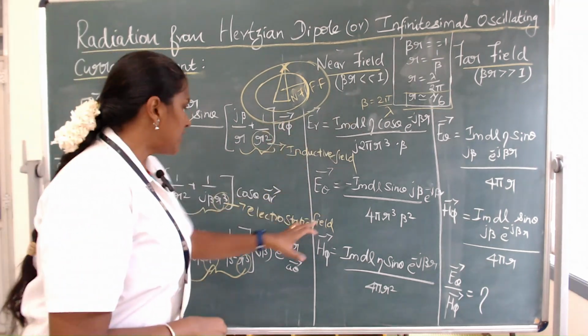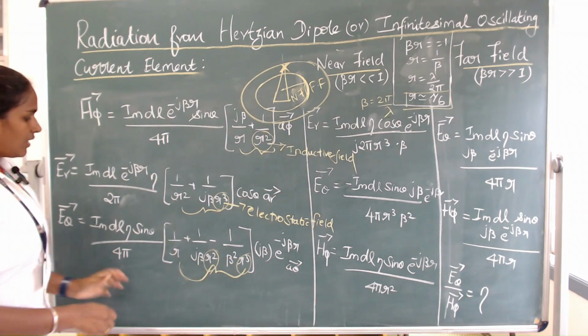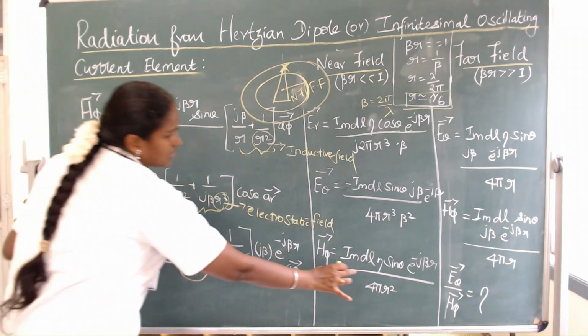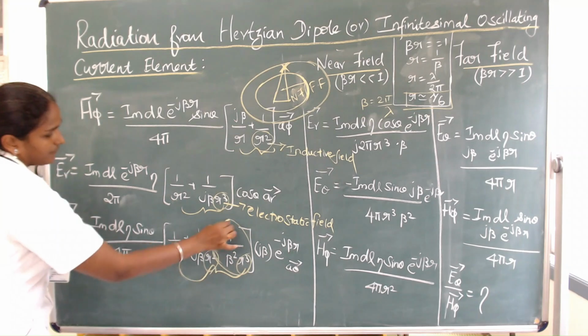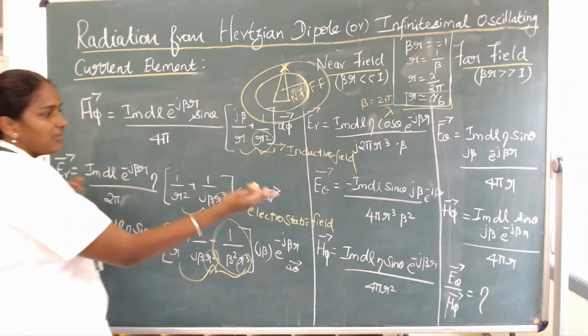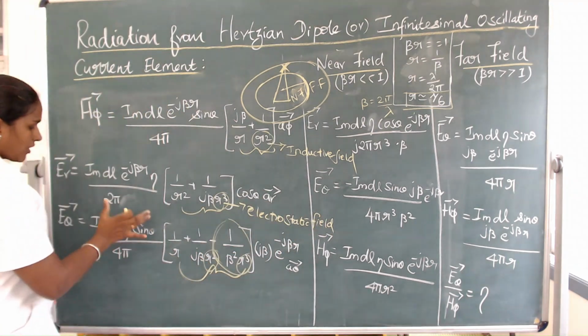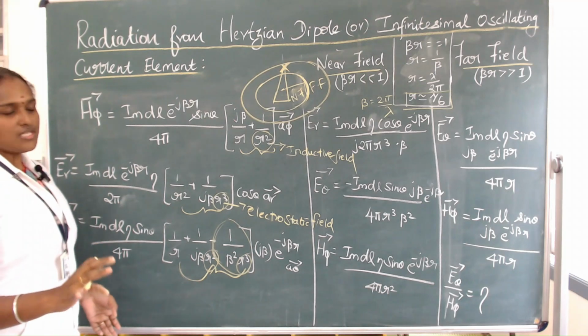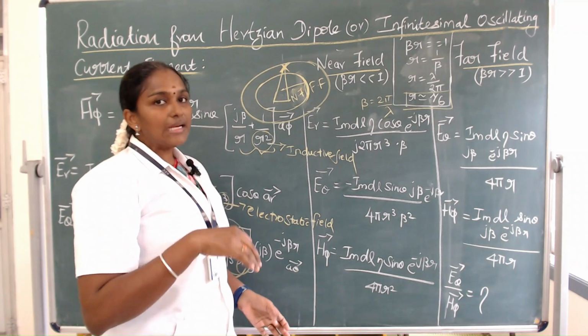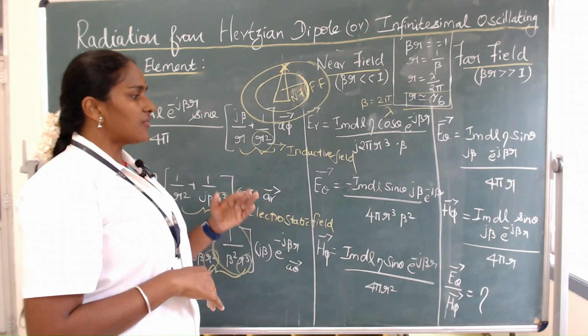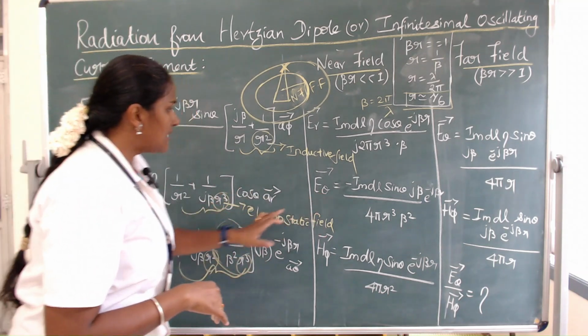Similarly, this is the general E theta equation. This term again exists similarly here. Only this term is taken. All other terms are neglected for near field conditions. But this constant term will follow for all conditions. Only the 1 by r reciprocal distance term has to be neglected or included based upon near field or far field conditions. So here E theta is reduced like this.